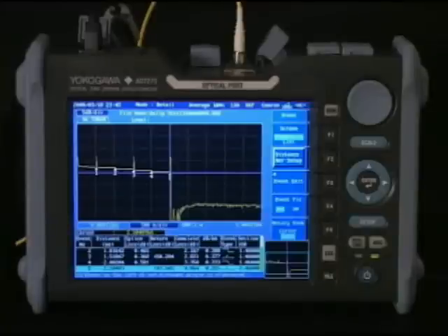If you happen to connect a fiber that has a signal on it, an alarm will appear. You should follow your company's procedure on what to do when disconnecting a live fiber. This is a very dangerous condition.